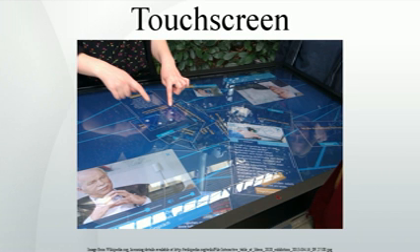Acoustic pulse recognition. The key to this technology is that a touch at any one position on the surface generates a sound wave in the substrate, which then produces a unique combined sound after being picked up by 3 or more tiny transducers attached to the edges of the touch screen. The sound is then digitized by the controller and compared to a list of pre-recorded sounds for every position on the surface. The cursor position is instantly updated to the touch location. A moving touch is tracked by rapid repetition of this process. Extraneous and ambient sounds are ignored since they do not match any stored sound profile.